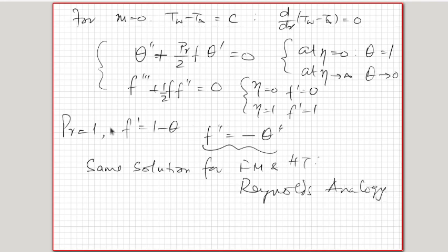And the temperature profile, theta profile, would be 1 minus f prime. So if I plot eta versus theta, and this is 1, the f prime was looking like this, so theta would be 1 minus that, so it will be 1 here and it will go to 0 as you go on. So this is your eta equal to 1.